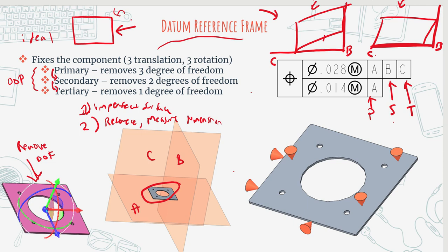But here's a crazy thing, which is that when you do the measurement, let's say you want to measure this point to datum C, and you want to measure this point to datum C, you can see that you're getting two different measurements here depending on how you did the orientation, whether you orient to B first and C, or you orient C first and B. So this might give you 0.05 as the distance here, because remember that we always measure the distance relative to the datum itself and not to the actual edge of the part.